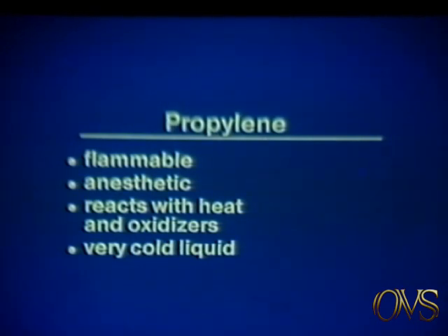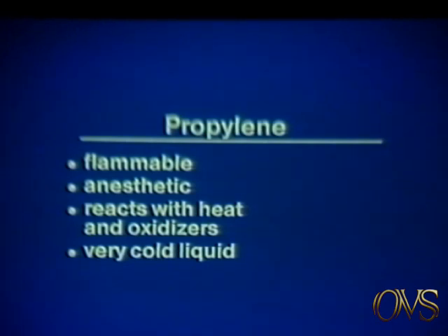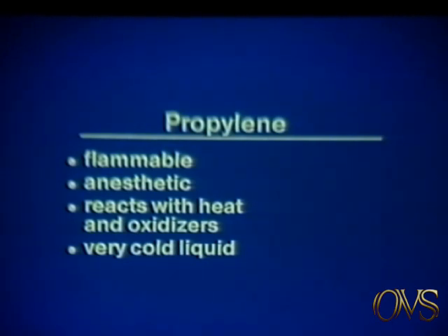Propylene may react violently with either heat, without a spark, or oxidizers. When working with liquid propylene, wear goggles and clothing to protect yourself from contact with the very cold liquid. If ventilation is inadequate, wear self-contained breathing apparatus.